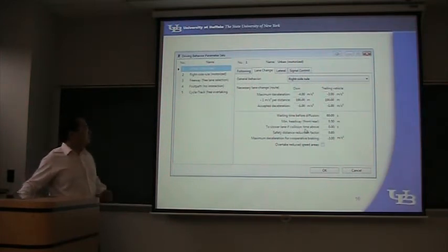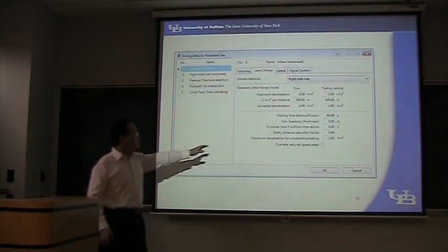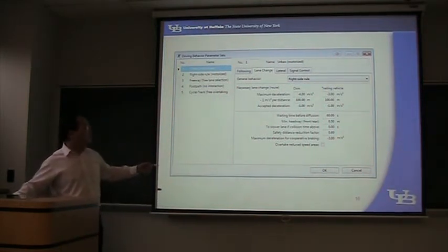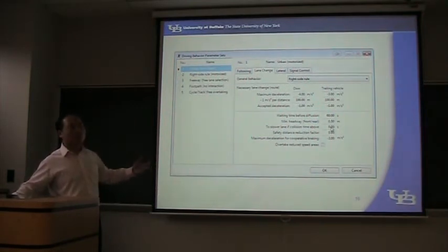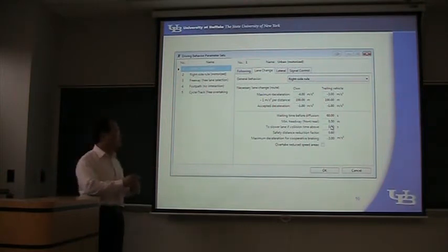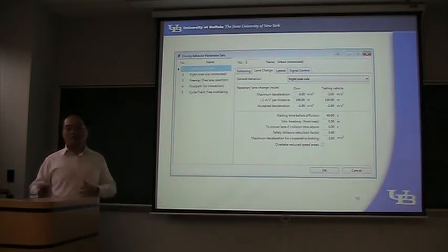The third one is called too slow lane if collision time above something. This means if you cannot avoid collision in the fast lane, for example, if in the next second you are going to have a collision, then you go to the slow lane. By default it is 0, which is no use. But if you specify this, then the vehicles will move more intelligently. They will avoid collision. They will make the lane change to avoid collision.